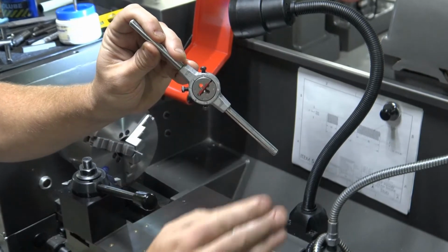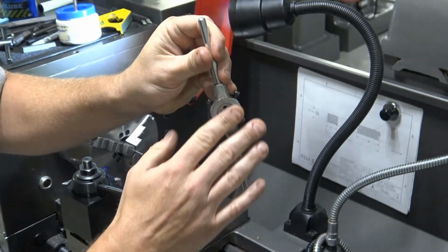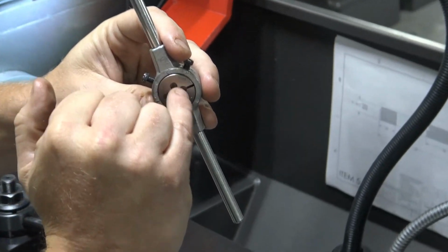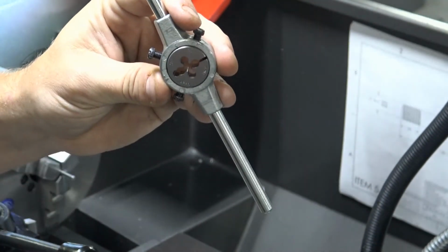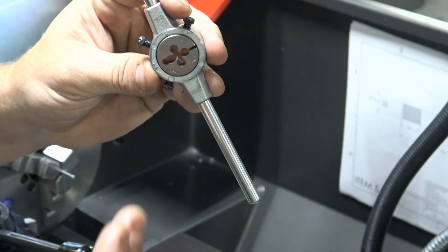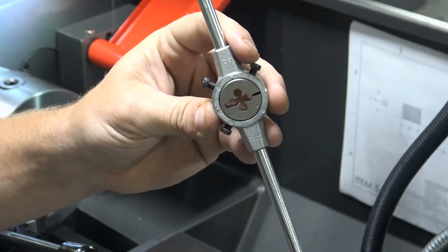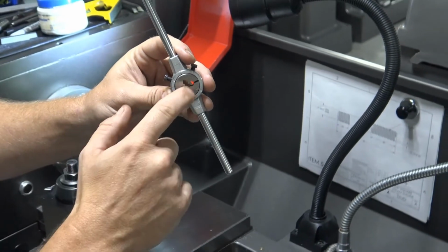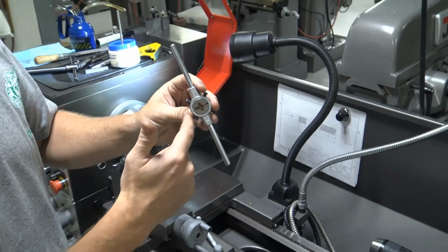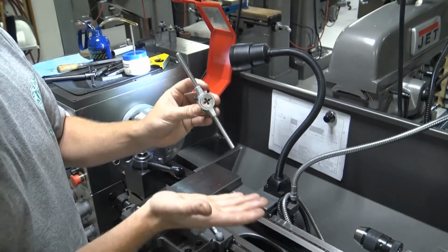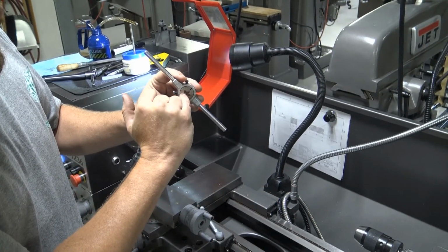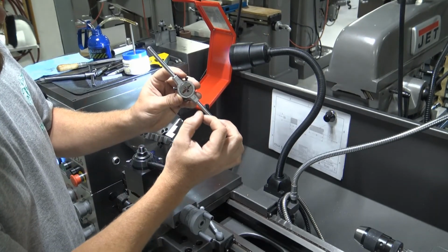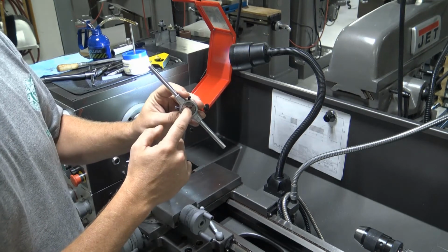So there's a front, there's a face like this, and there's the back side. We always want to feed it in here. If you look at the very center of this, there will be a little bit of a lead-in, and the lead-in is helpful for us to get the thread started. So you choose the side that's got the lead-in for the threads. It will look kind of like a cone shape, and you'll see that it's not fully formed threads, because it's actually bigger than the thread size. So that's the side we want to go on.